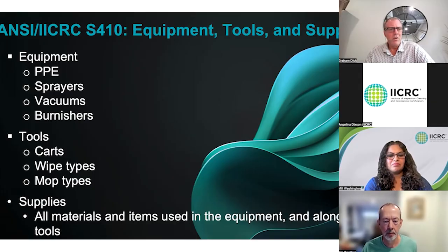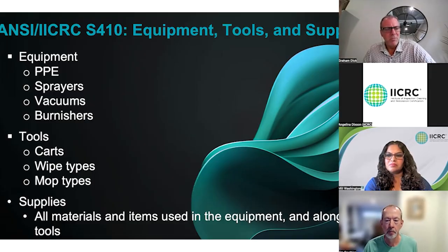After doing water damage in hospitals for the last couple of decades, I can say that almost every time I've removed vinyl cove base after a water escape, I find pre-existing mold. And I came to the point where it's like, okay, this is mop mold. It's from overly wet mopping practices.